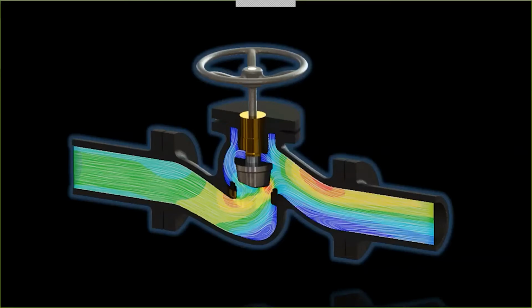Internal studies, or internal flow, are the kind of studies that would be most relevant if you're designing valves, manifolds, piping systems, and such things. In a previous webinar in the spring, I discussed a poppet valve I designed 5 years ago without the use of any flow software. I was able to show how the fluid flowed through the valve, how much pressure was lost in the valve, where that pressure was lost, and you could see that I could have done a better job had I had a tool like this to begin with.